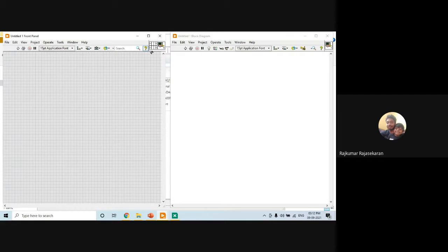Okay, but let's say you want to create your own BMS. In that case we need to go for a data acquisition system which can make measurements of the battery. Right now I'm just using very simple hardware. But most of the time, to first prototype the BMS, we'll be using specialized hardware which can make measurements up to 1,000 volts. We should have a DMM which can measure up to 1,000, 1,500, or 2,000 volts DC. Something like that.